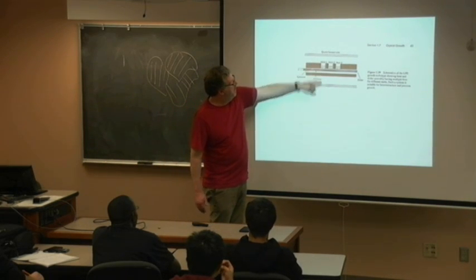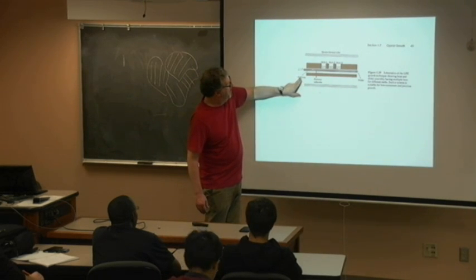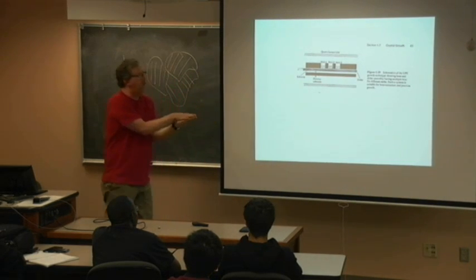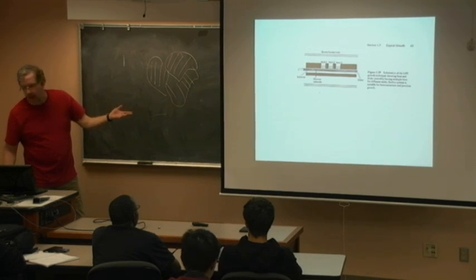You start off with a liquid, and then the liquid comes in contact with the substrate. So you slide this underneath and they come into contact, and as you slowly cool it, it condenses. That's liquid phase epitaxy. We used to do that in my lab, but then we stopped.